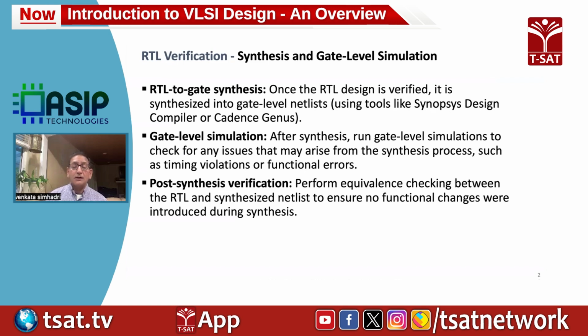You can also, there are also tools called equivalence checking. So you can take your RTL and do an equivalence check with your gate level netlist to make sure that the performance is not affected, the functionality is not affected, when you're converting your RTL into a gate level netlist.